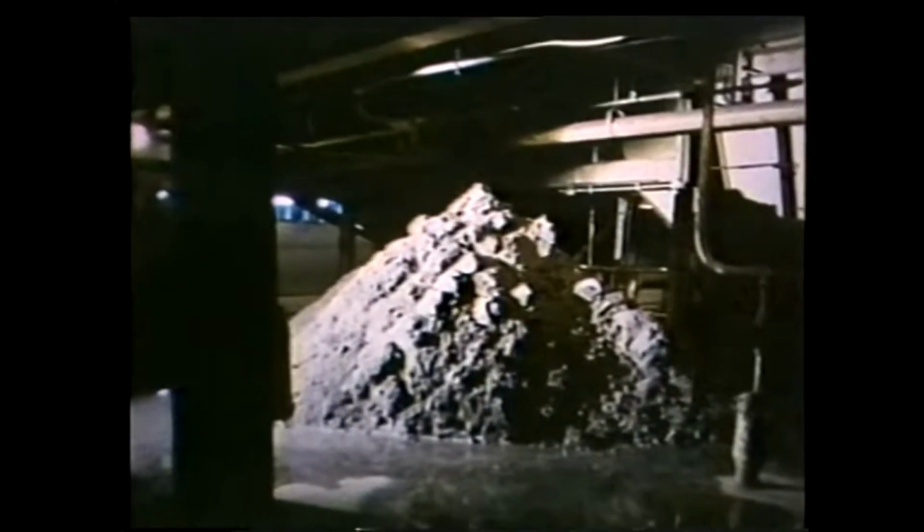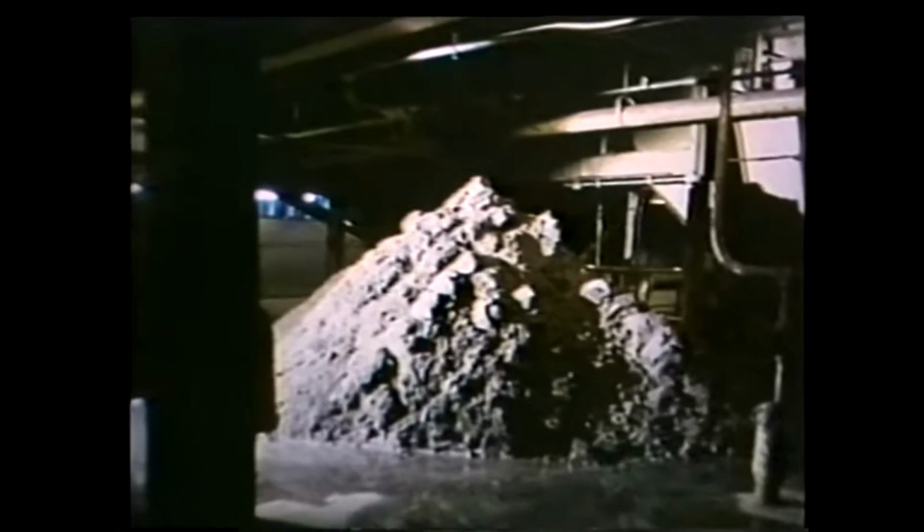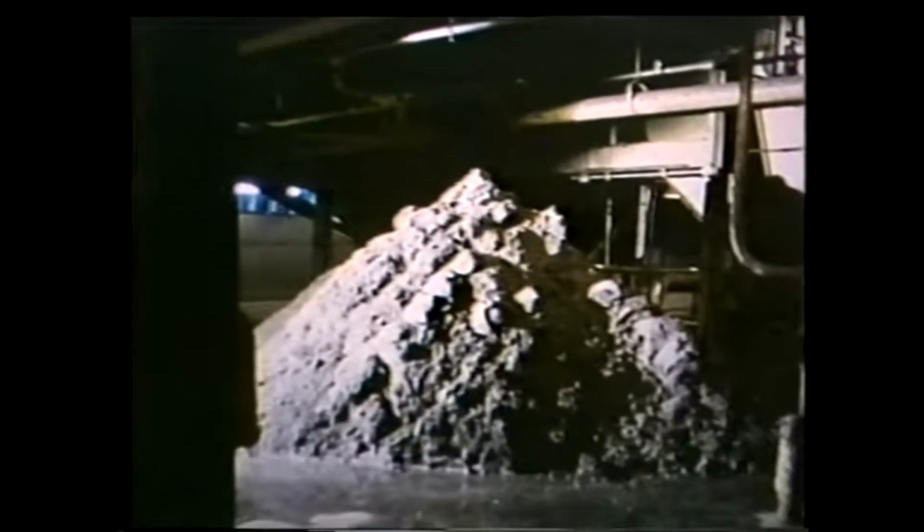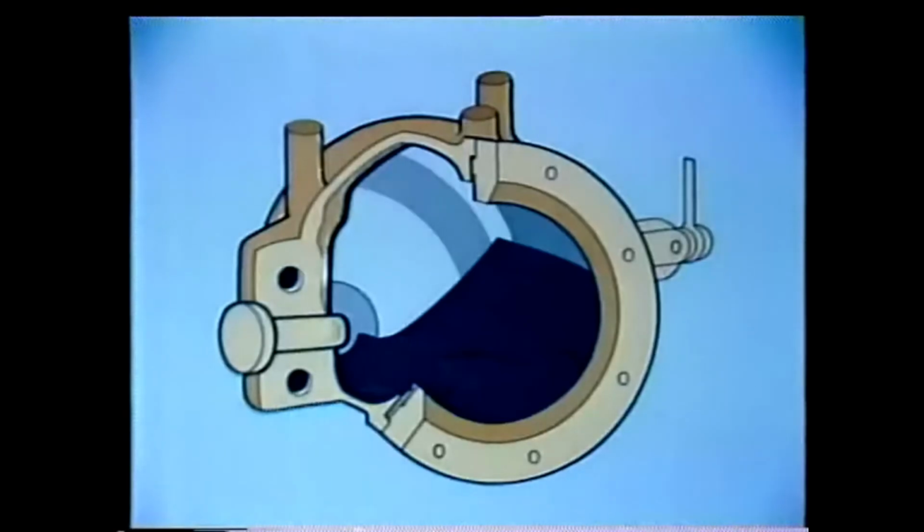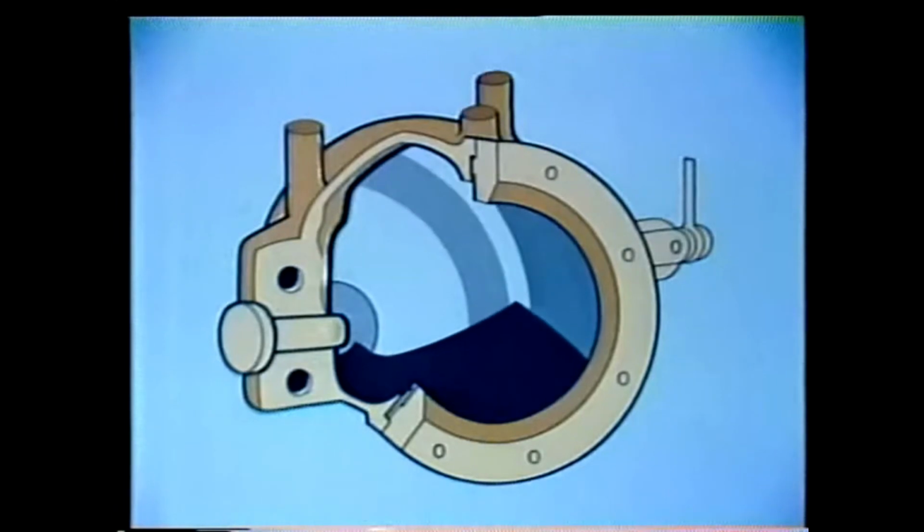Well, this is a common ball valve, a type of basic valve we talked about earlier. A special variation of it is the V-ball valve. The V-ball valve is finding wider use because, like the pinch valve, it has very low pressure drop characteristics and does not slow down flow through it.